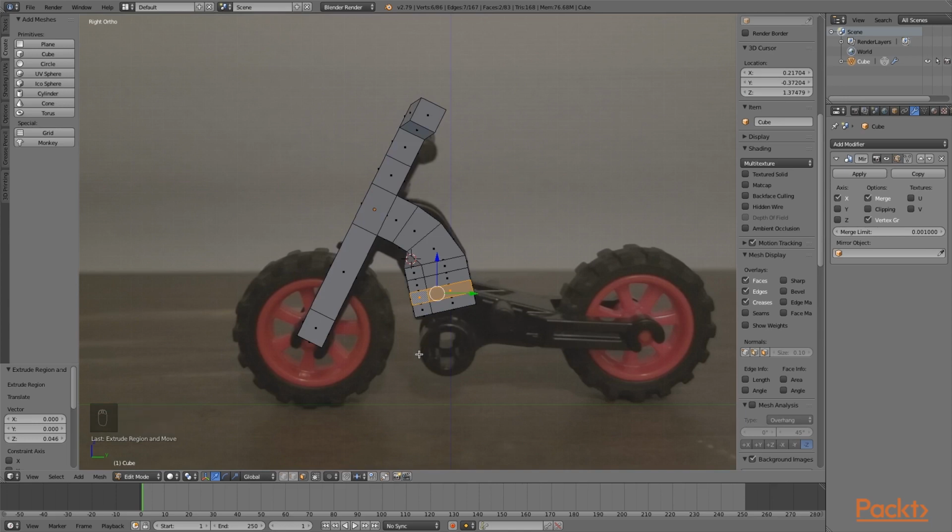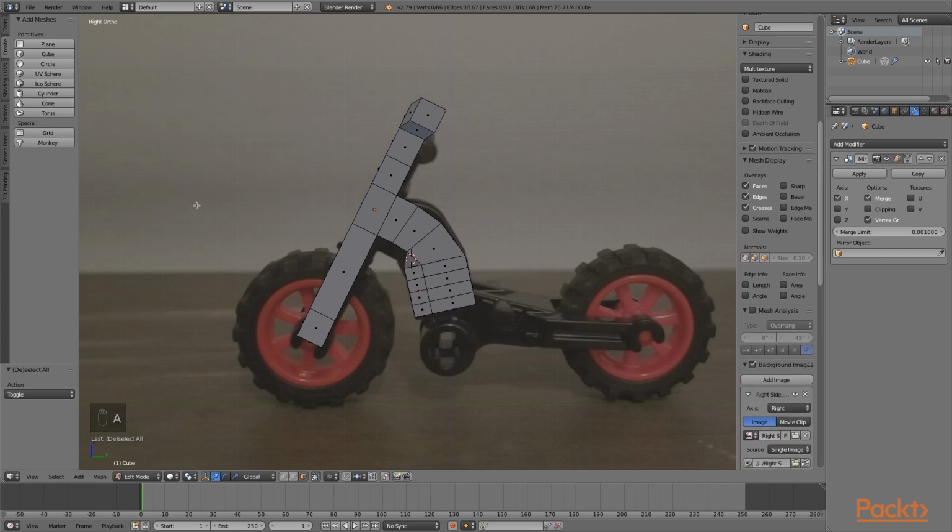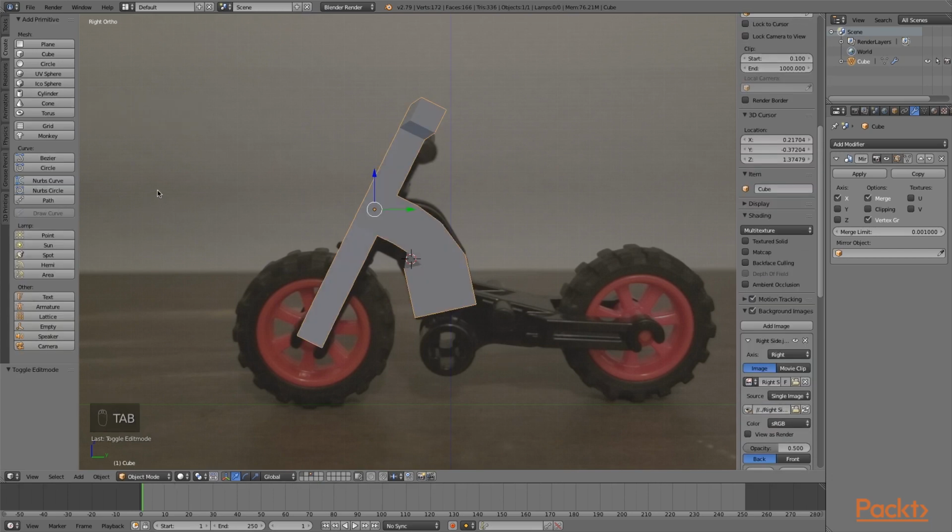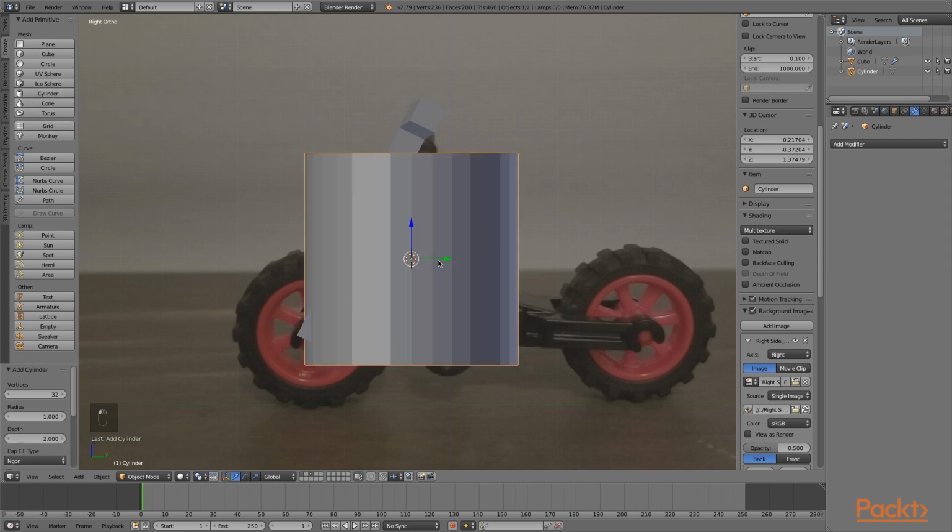And now we want to build this circular thing here that we have. I guess that's where the bottom of the motor block is. So what we can do is use a cylinder at this point. We connect the two objects. So I'm going to go over here to my create panel. I can create a cylinder. Go ahead and deselect everything. Tab back over in object mode. Deselect it with A. And then create a cylinder. And it's going to pop out right here where our 3D cursor is.